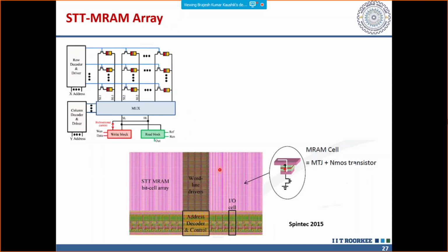And this is the tape-out that they had shown, where each of these cells contained a transistor and an MTJ put together. That formed your MRAM cell. So the technology translated from material to device MTJ, and then from one device MTJ to a memory cell. And this memory cell is then further translated to a complete array, wherein you could store a huge amount of information for a longer time without changing its content.